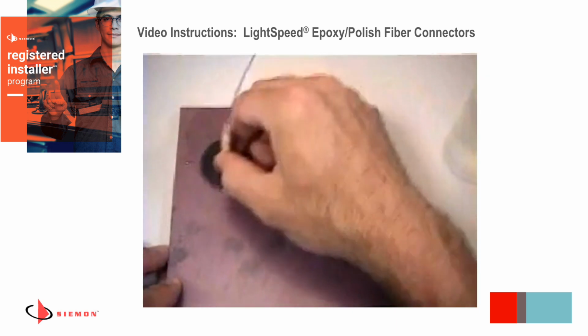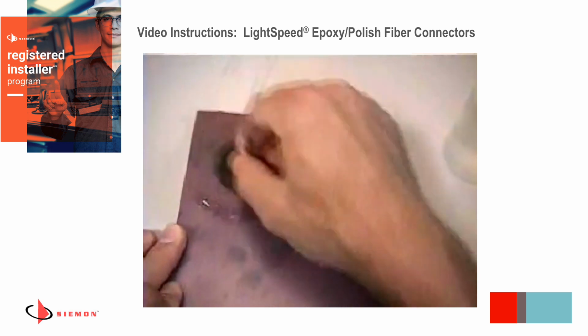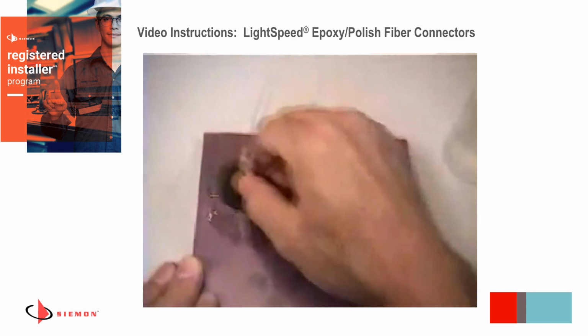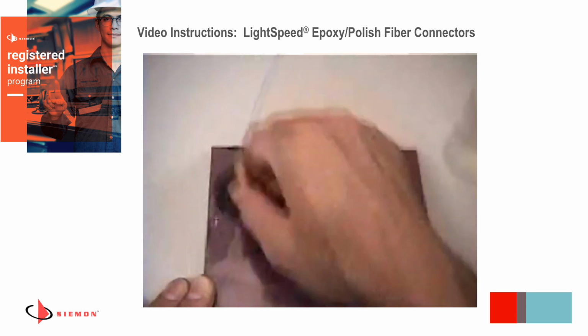Gently grip the connector, apply medium pressure, and polish the tip in a 50 to 75 millimeter or 2 to 3 inch figure 8 pattern for 25 to 30 revolutions. For best results, avoid over-polishing or using excessive pressure.